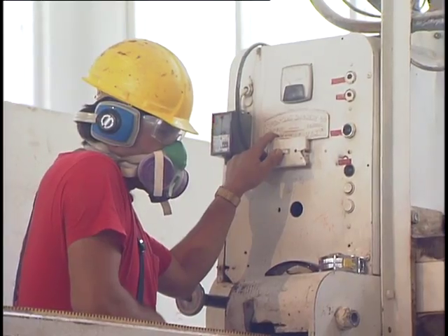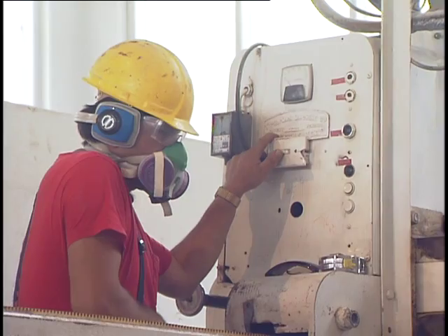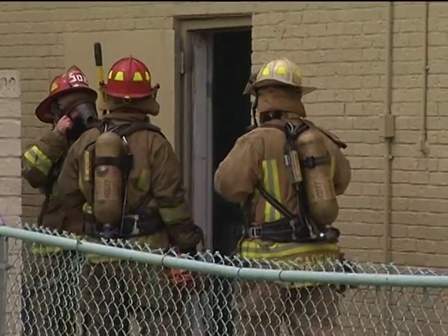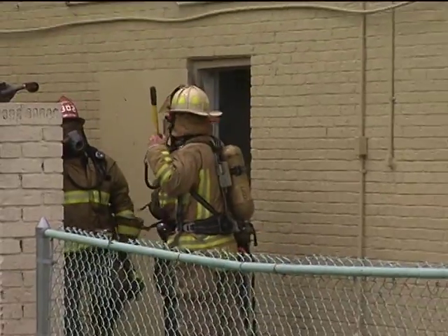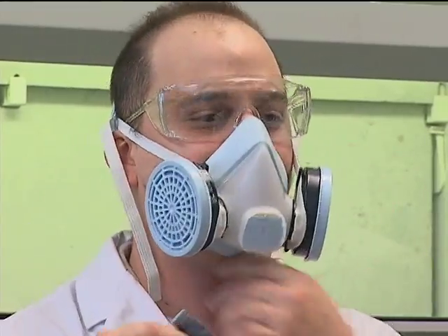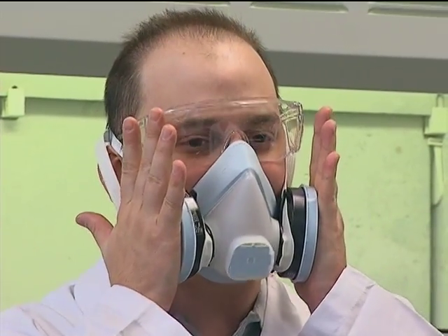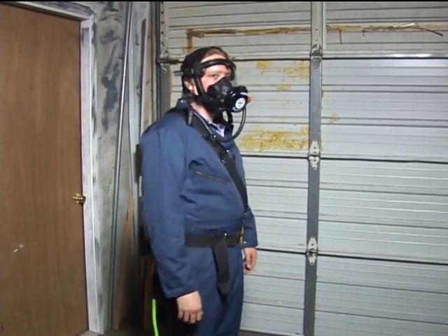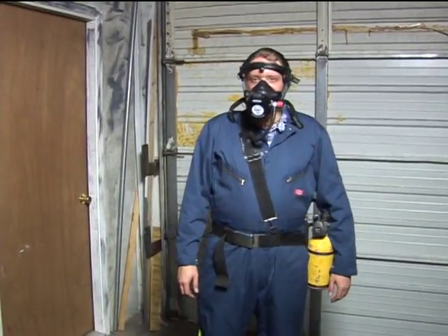The user of the respirator is another important factor when considering selection of a respirator. Wearing respiratory protection poses a physical burden on the wearer. When a worker's medical condition would prohibit restrictive breathing conditions, negative pressure respirators would not be an appropriate choice. Worker preferences should also be a consideration during the respirator selection process.